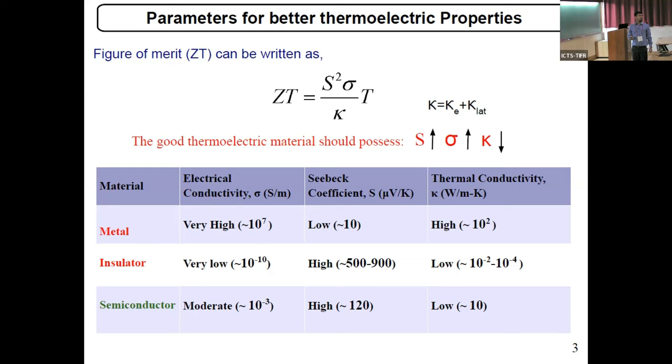So for a good thermoelectric material, electrical conductivity and thermal conductivity both should be... they don't need to be high, right? No, if the electrical conductivity is higher, the thermal conductivity has to be lower. If both are higher, then it cannot give a high thermoelectric figure of merit. So that is the challenge in thermoelectric materials. Okay, thank you.